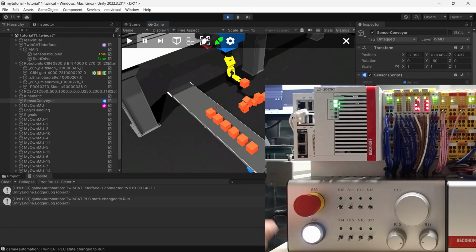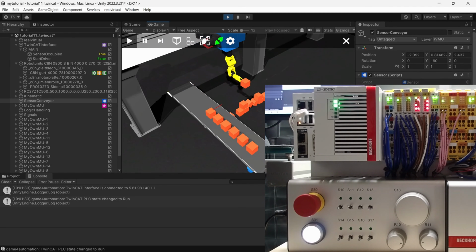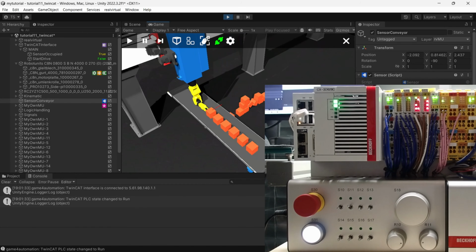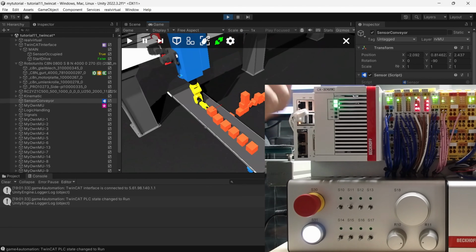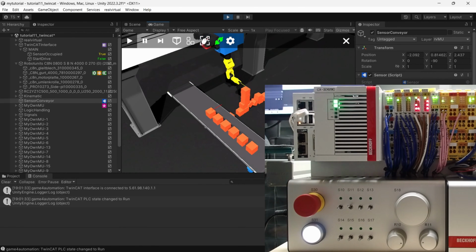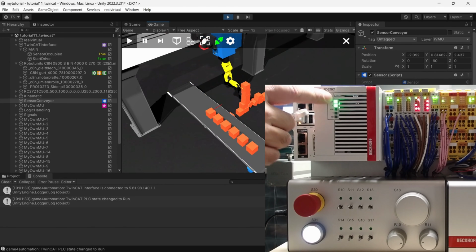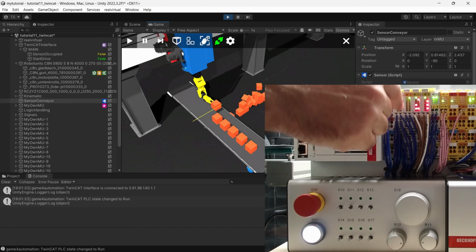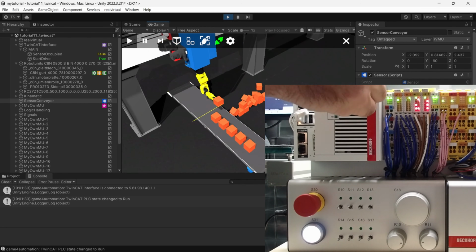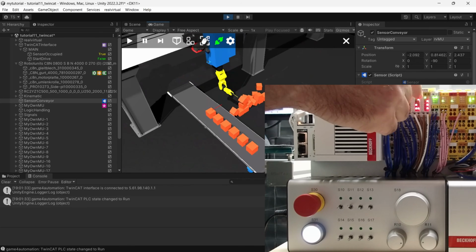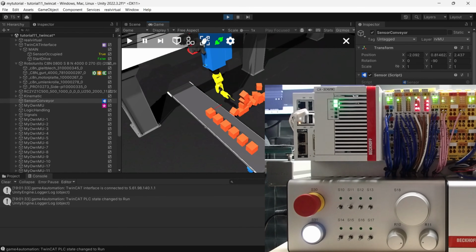That's how I could use it. Or, for example, I could use it also if I would like to do, I would say, 3D HMI. So deliver a 3D model with the real machine connected to the PLC. So the 3D HMI within Unity, real virtual, will communicate over I/Os or symbols, signals, which are not connected to any of the I/O devices, whereas the real machine and real HMI is connected via this.